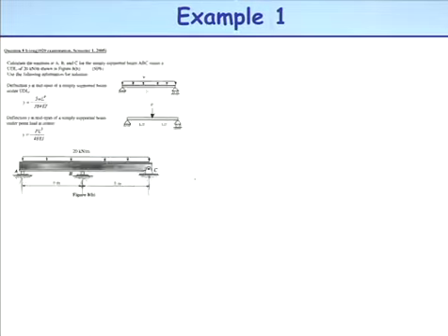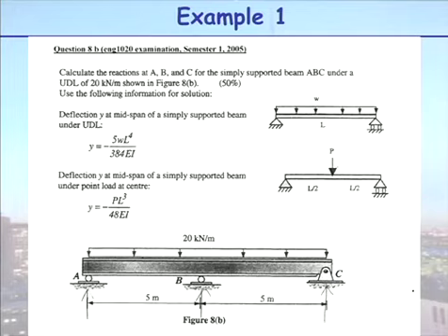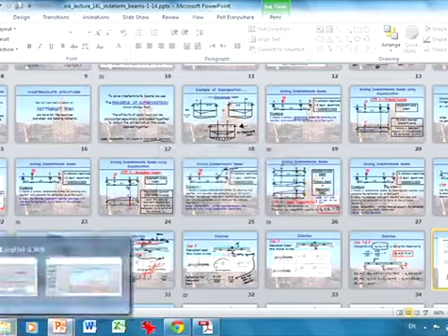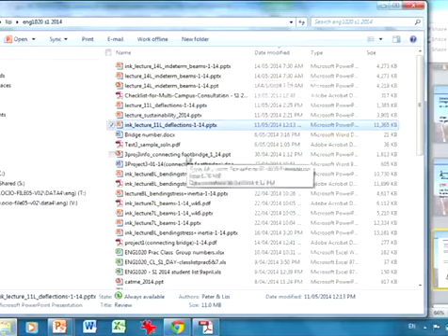Okay, now in saying that, how about I break and I talk about the project now? So, in the project with task 3, you have the choice where you have basically 3 columns and your beam runs continuous over there. So this system here, 1's a pin, 2 a roller, you've got 4 unknowns. So what you need to do there is you need to draw the bending moment diagram for this system. When it comes to calculating the deflection, it's too complex to do. So you have been given the formulas. Let me find the project brief.